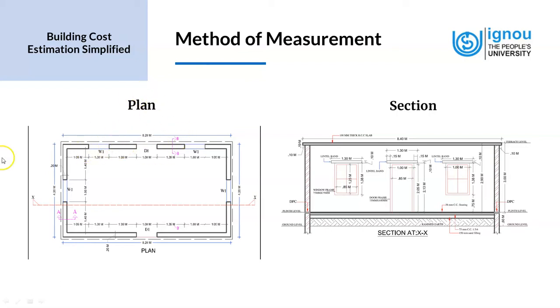We also see that there is a dotted line going around the room, and this represents a part of the room that is not visible in the plan. So this represents the extension of the roof slab, the projection of this roof slab. The dotted line indicates that it is not seen in the plan, it is hidden in the plan, but it exists above the level at which the plan is cut. So the dotted line represents the extension of the roof slab.